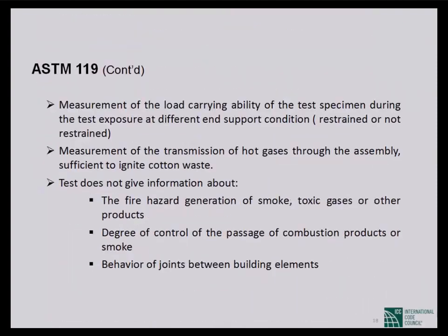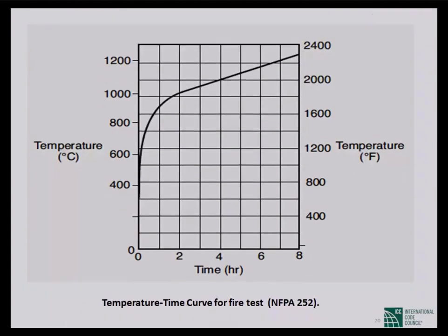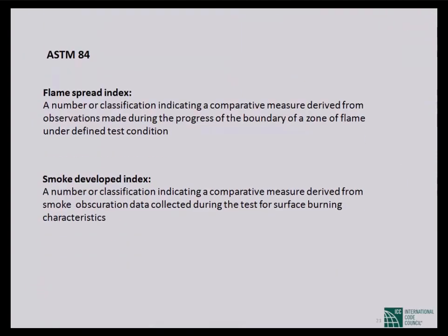So when we test 3 hour, 4 hour, 1 hour, that means it will withstand an endurance load, it will withstand a hose stream pressure, and similarly it will withstand a definite type of temperature. So I think you have understood that the rating of a material, element, or structure is not only the temperature, not only the hour, it is load, pressure, and other things. When it is actually tested, all these parameters are tested and reported.